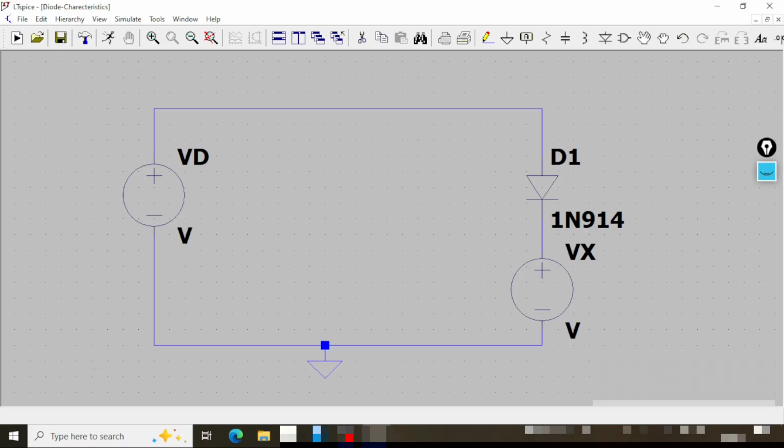We have selected the diode type, and the various parameters are set there, so you don't need to tweak the parameters. This model is available in any LTSpice version, so you can pick it when you are doing the exercise. I will be using different diode models because when you are designing an analog circuit in real life, you have to pick up the components, and you go to their datasheet, where you will have the specification of that particular device. From there you can select their models. That will help you get a circuit which is desired, with all the components according to your basic calculation and specification.